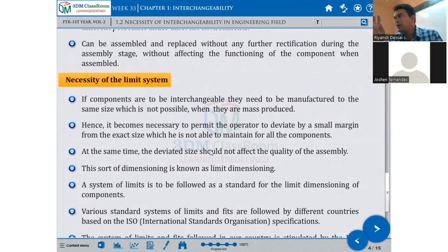For a bearing or shaft, there is an upper limit and a lower limit, and you have to manufacture that product within that limit. The jobs you do have tolerances. Tolerance means plus and minus dimension, like plus or minus 0.02 or plus or minus 0.04 millimeter. Means for 60 millimeter you have to maintain that dimension within that tolerance or limit. Then 60 plus is acceptable. If it goes over the limit, beyond the tolerance, it is rejected.